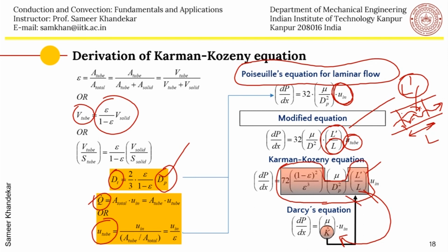The permeability has to be experimentally calculated. So applying the simplest capillary limit, on the left hand side you have the capillary pressure drop, you have the gravitational pressure drop, this is the plus, and on the right hand side you have the delta P liquid, which is coming from Darcy's equation, and the delta P vapor, either it is laminar or turbulent.